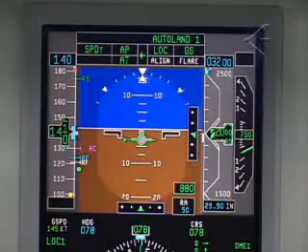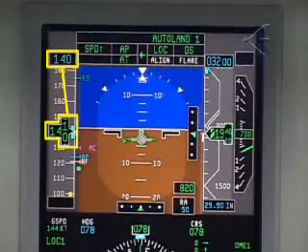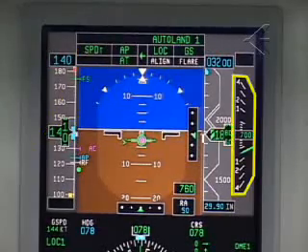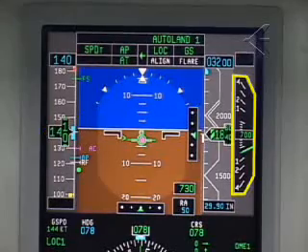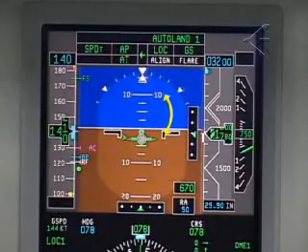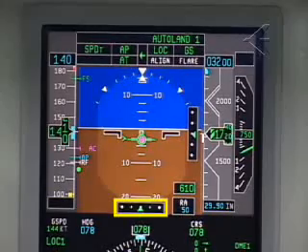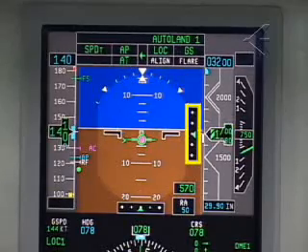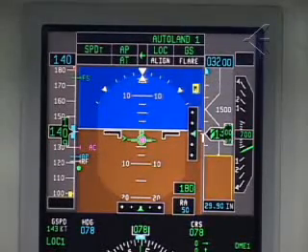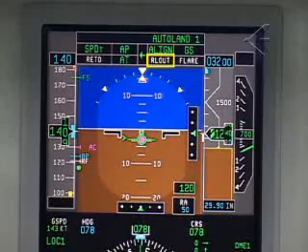The pilot not flying should be monitoring and call out for the go-around in case speed is 10 knots above the target speed or 5 knots below target; vertical speed is greater than 1,000 feet per minute; pitch is greater than 10 degrees or less than 0; excessive localizer deviation greater than 1/4 dot; and excessive glide slope deviation greater than 1 dot. At 150 feet radio altitude, the align mode automatically engages and the rollout mode arms.